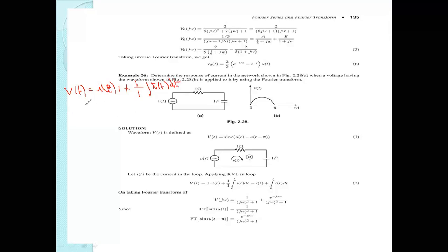So V of t is equal to I of t plus the integral of I of t dt. Both the resistance and the capacitance given are only one. Apply the Fourier transformation on both sides. V of omega is equal to I of omega...